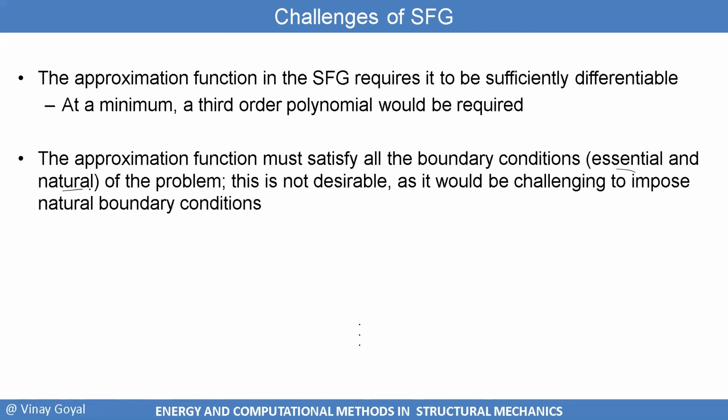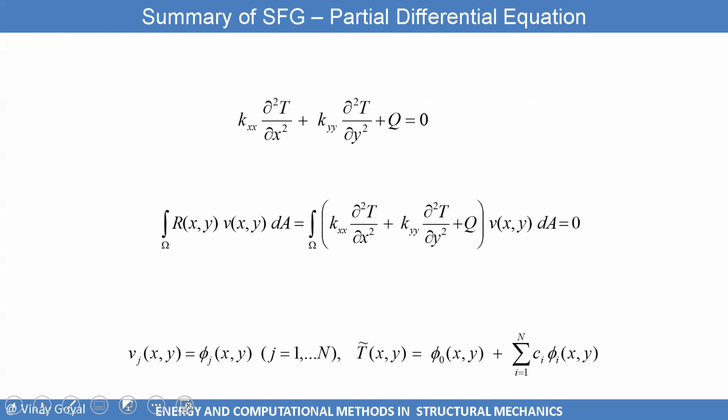That's not desirable because imagine if I have to impose all the boundary conditions, essential and natural, that'll make it really difficult to come up with an approximation function that can be used. And so it's not a preferred method, and finite elements really is based on the Rayleigh-Ritz or the weak form Galerkin. But the strong form Galerkin is important to understand because it provides the fundamentals on where the weak form Galerkin comes from in the first place,